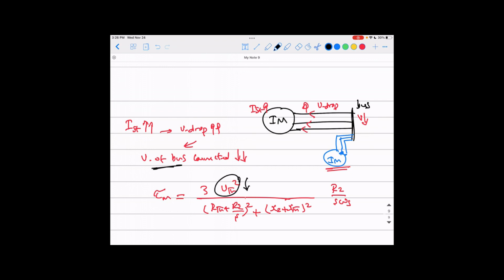And while the Thevenin voltage goes down, the torque of your motor goes down, remember? So the torque capability of this other motor will drop down so much. So if it has a heavy load connected to it, it maybe will not handle this load. Maybe the motor will be burned.